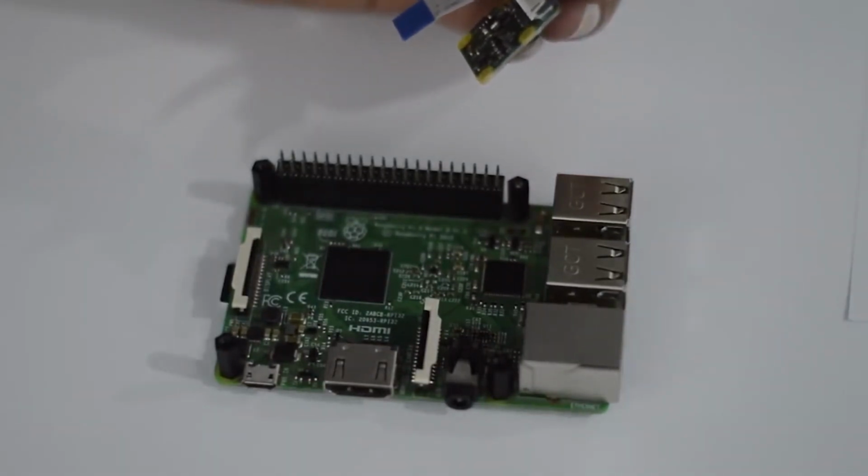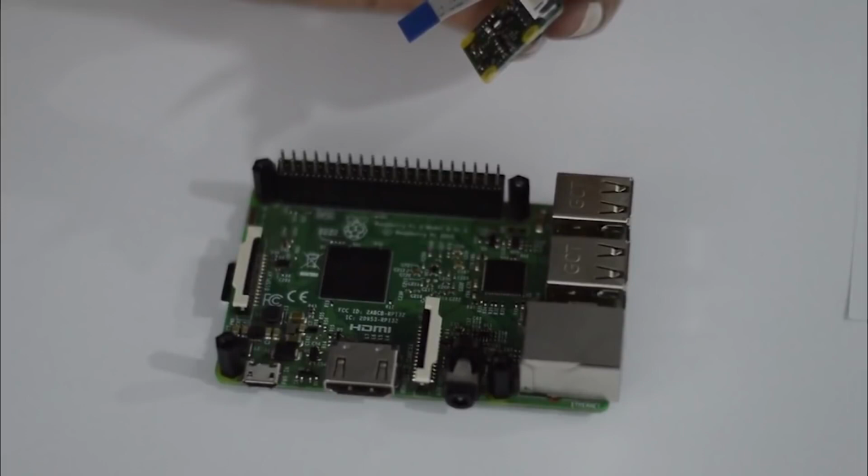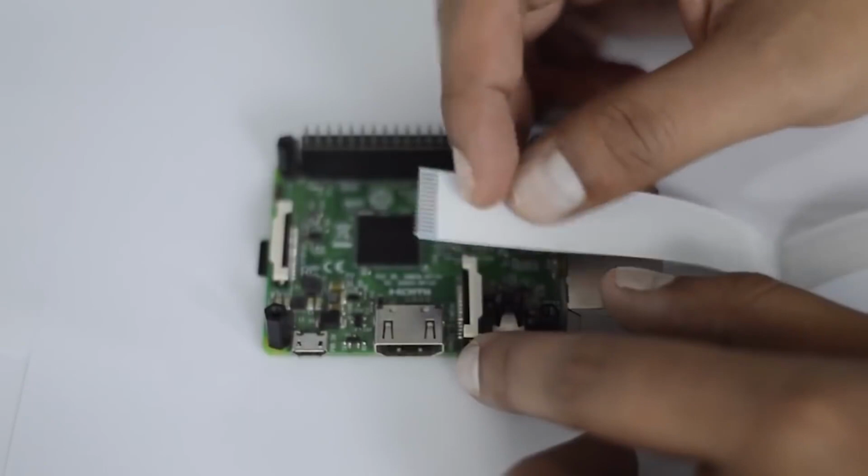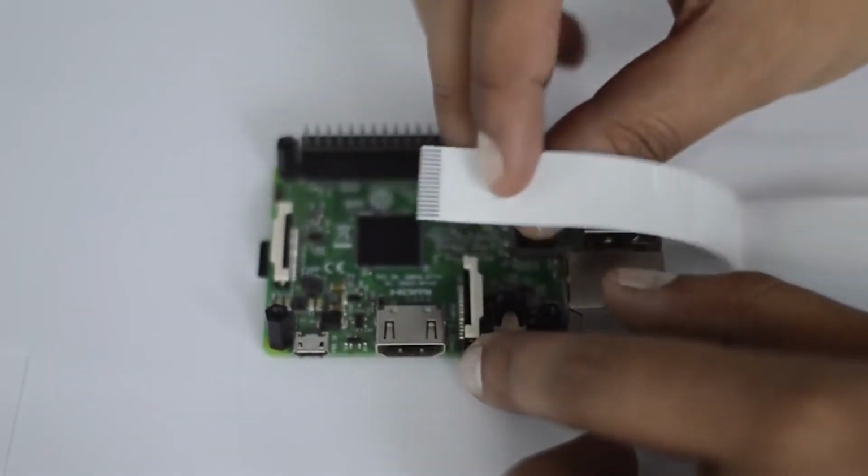There are mainly 2 precautions that you really need to consider while working with the Raspberry Pi camera. One thing is, please ensure that the Raspberry Pi is switched off or disconnected before you connect the Raspberry Pi camera. Otherwise there is a high chance of blowing up your camera. We've already successfully managed to do that once. So please ensure firstly that the Raspberry Pi is switched off and also that the connection is correct. The silver side present here should be facing the HDMI port that is present here.